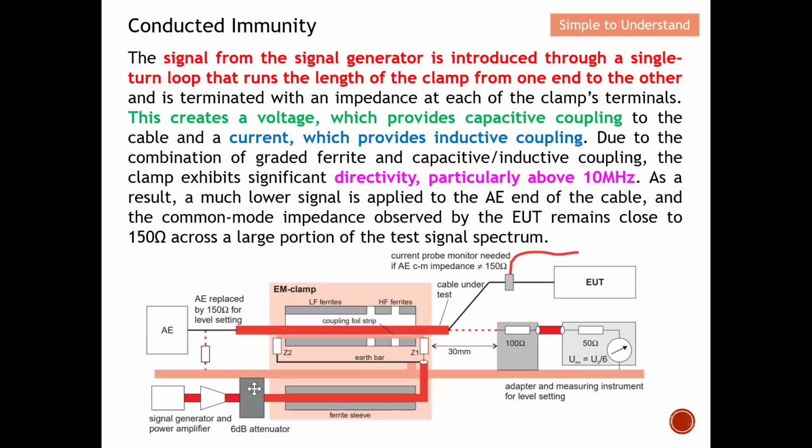So in short, because you need the signal to travel from one location to another, you need to have a potential difference. Once you have a potential difference, you induce a capacitive coupling, and the coupled signal couples over to the conductor of the cable, and therefore a current flows. So when a current flows, you also induce the inductive coupling.